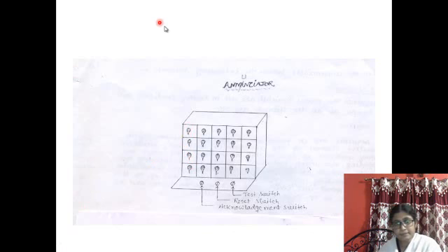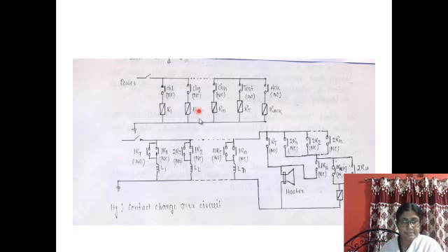So if all the process control loops are in healthy conditions, connected to all the different channels, then all lamps will be in off state, because a similar mechanism is used for R1, R2 to Rn. All have NC type contact, and then lamp L1 is connected. Before discussing the other contacts, let's get clear on when the lamp will glow.